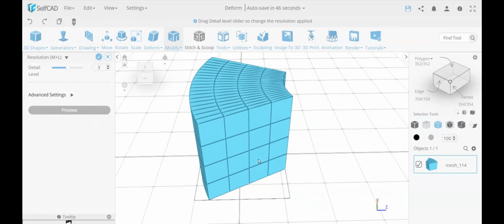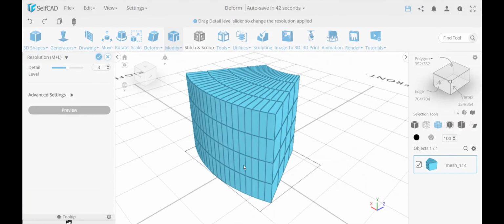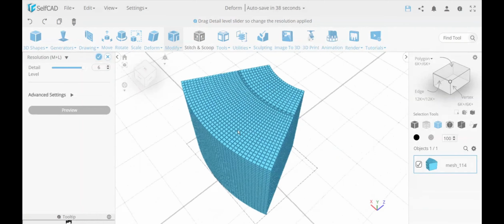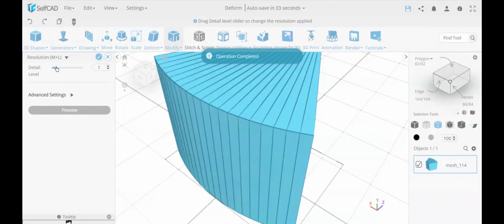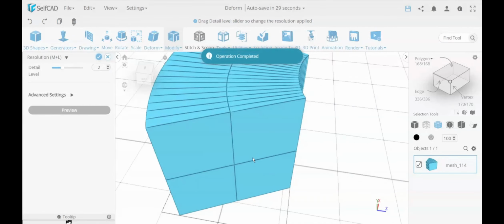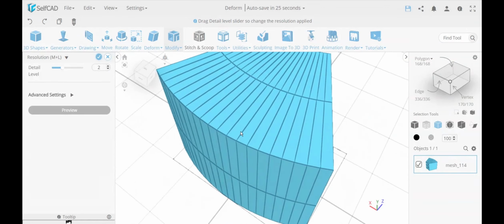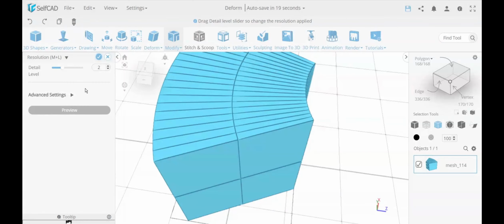look what's happening over here. It doesn't split anything in this direction, only in this direction. Regardless how big, how detailed I make it, the faces stay kind of uniform a little bit. If I split a little bit, it splits only where it's needed. If I keep splitting, it splits it over here and over here. It doesn't reduce the details, but it doesn't add additional details either. It keeps it. If I go to uniform, as I've shown before, it's actually going to keep it uniform.